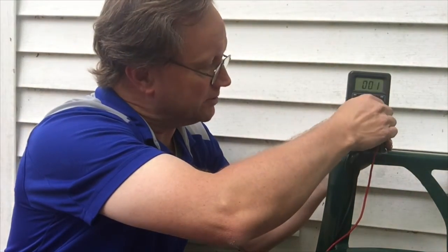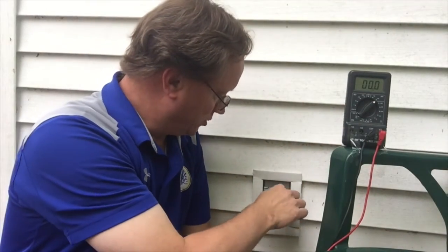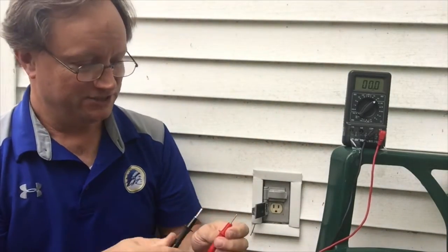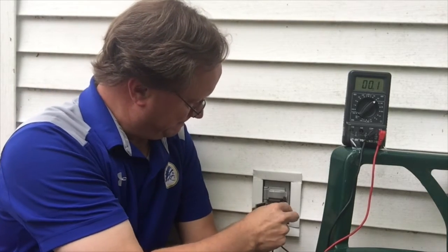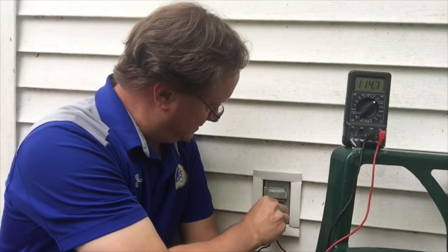Electrical outlet. I'm going to take our meter and I'm going to switch the setting over. I'm going to open up our electrical outlet, which is another reason why I sat here, because I'd have easy access to it. These are designed to do this. So I'm going to meter the outlet. When I put the probes in there, we are reading about 121.3 volts, joules per coulomb. 121.3 volts means 121.3 joules of energy per coulomb of charge that is made to flow.